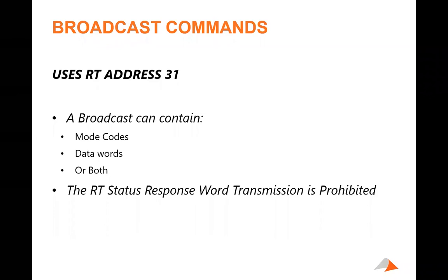The design standards, most of the time, say you should have at least a portion of your standard messages going over your redundant bus so that you can make sure everything is operational in case you have to switch all your messages over there. For people who need the data to be even more robust, you could transmit it on A and then transmit it on B, but that's a design decision.